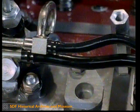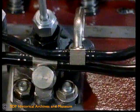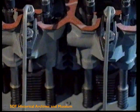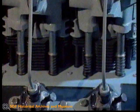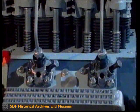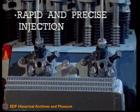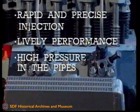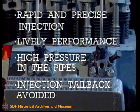A return valve stops the injection, makes the fuel return from the injector to the pump via the same delivery pipes until the pressure drops to 70 bars. At this point, the valve closes and the delivery pipes remain full of fuel at 70 bars, ready for immediate injection at the next cycle. Rapid, precise injection. Lively performance. High pressure in the delivery pipes, even at low speed. Injection tailbacks avoided.